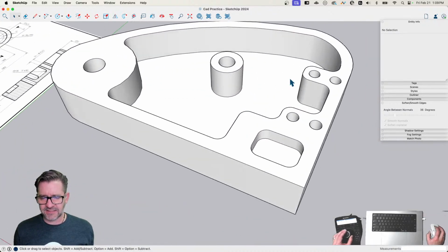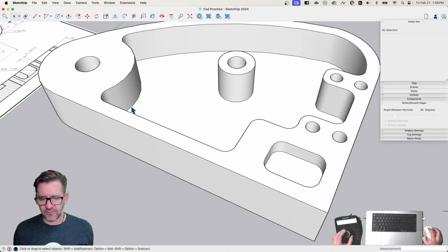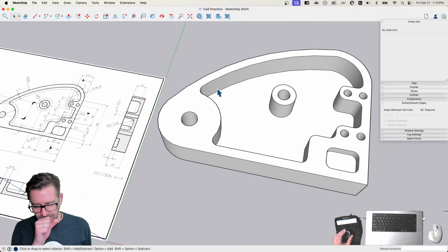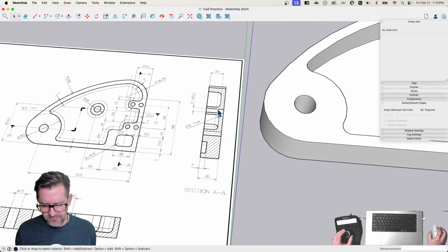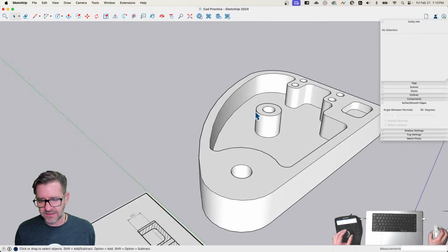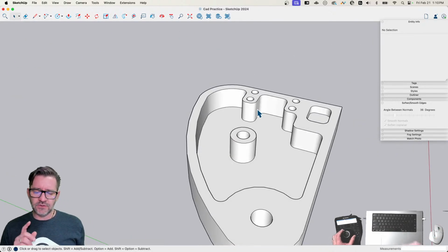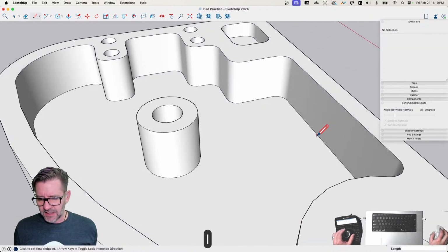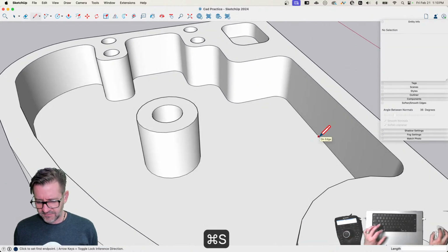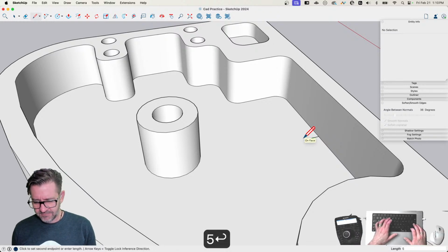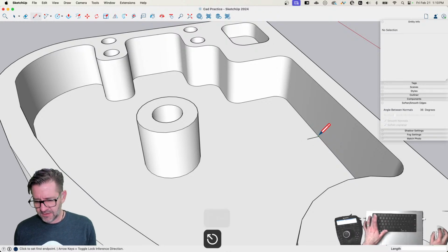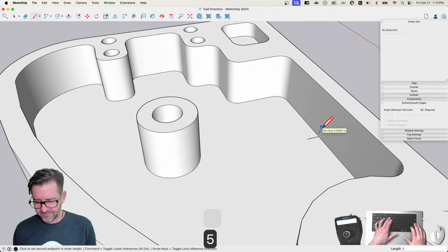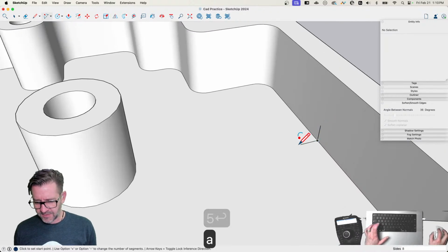And then yes, the last thing we're gonna do is we're gonna come in here and round over this interior corner right here with a radius of 5. Hey, that sounds familiar. All right, so when you do this, this is how I would recommend. I'm going to come right here. Come this way 5. Right here. Go up 5. And then I'll take my arc from here, here.